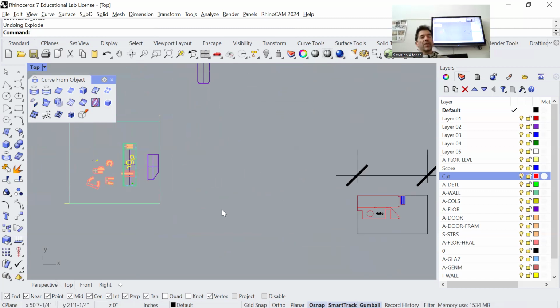So it's a slow process of exploring and extracting the borders and then collecting them on the surface of the laser cut. There's no magic, everything is not done for you, unfortunately. Even though Grasshopper will come in and help in terms of exploring all of these surfaces, extracting the border of all of these surfaces, taking all of these borders and placing them in an organized way into the panel.